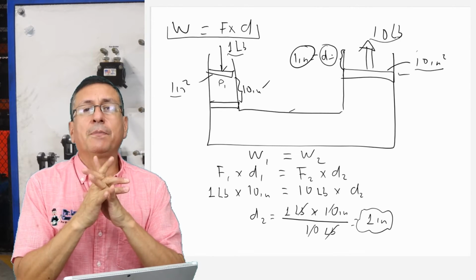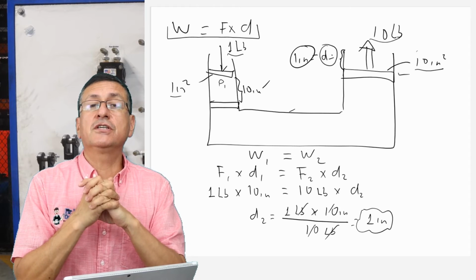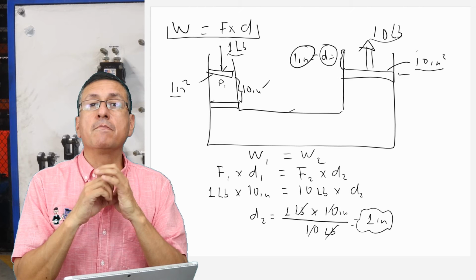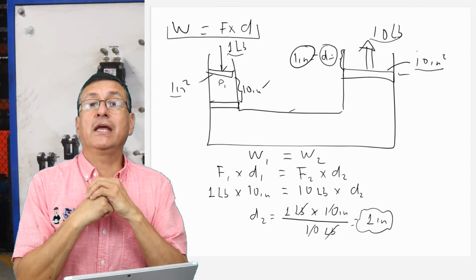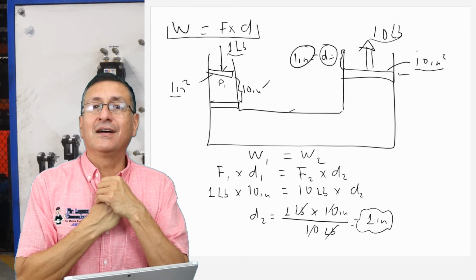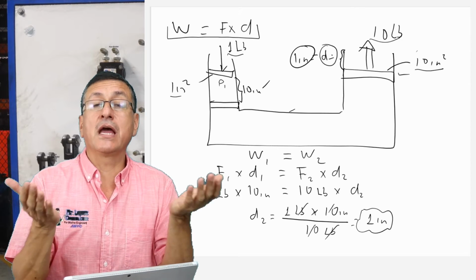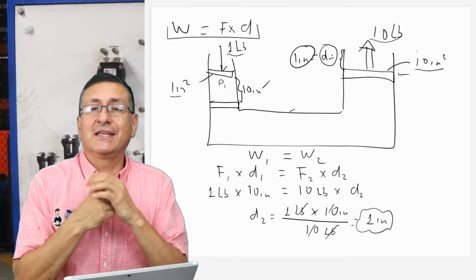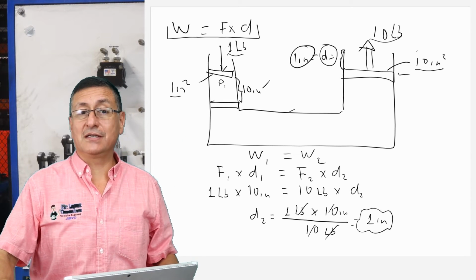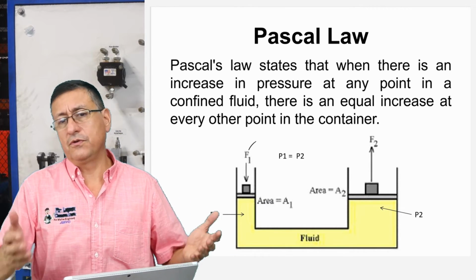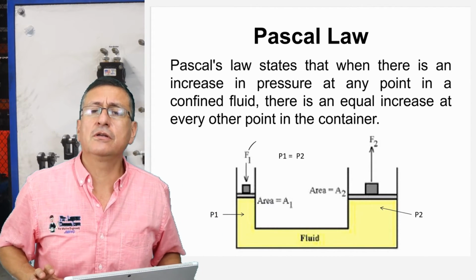In the chapter dedicated to the power steering system, the output force produced on the rod of the ram is critical in order to calculate how much torque I am going to create on the rudder. Because in some boats with a big rudder, like the sailboat, the torque applied on the shaft is critical.